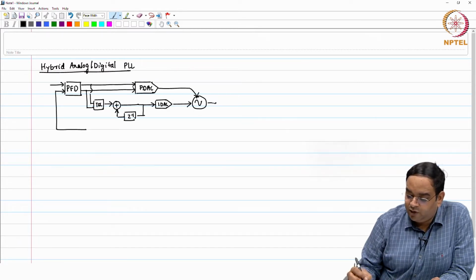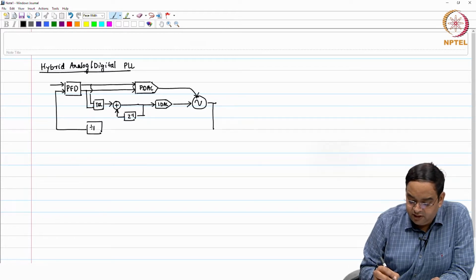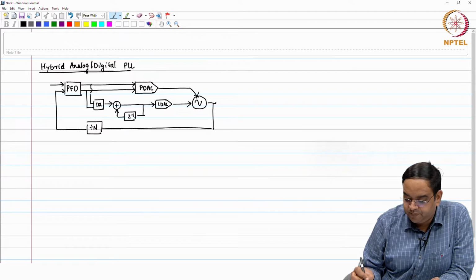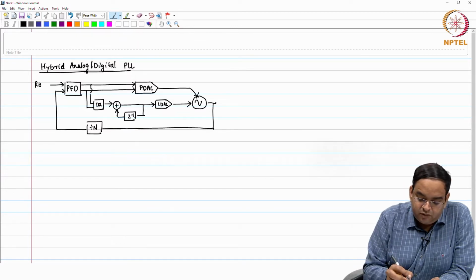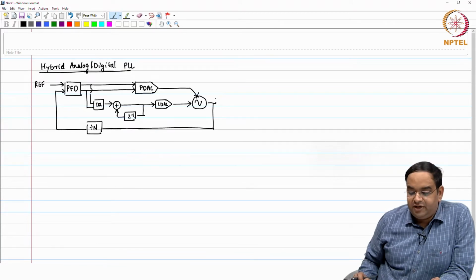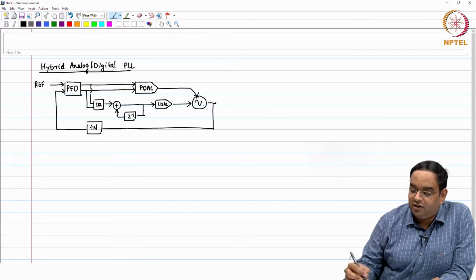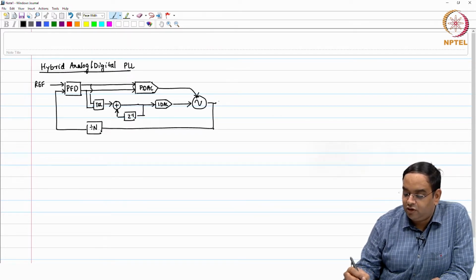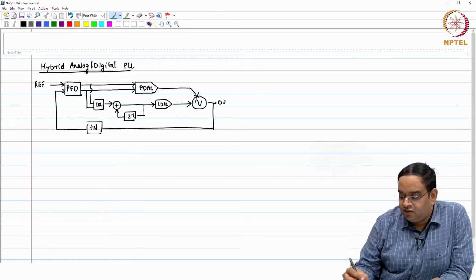Then the output of the VCO feeds back through a frequency divider. Here, what we have seen earlier is the implementation of the phase frequency detector, the TDC using delay elements or using a single D flip flop, and your current controlled oscillator also. So, this is your out.